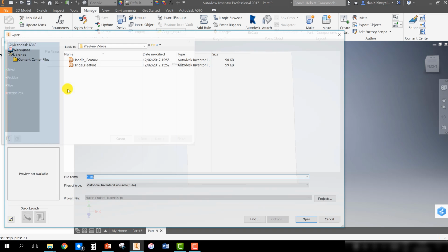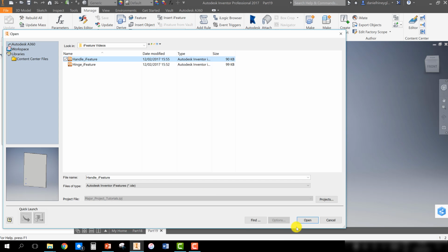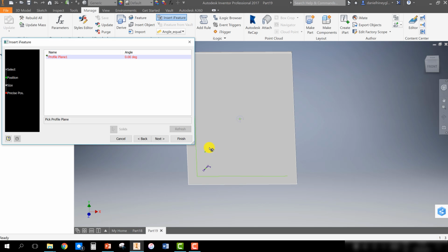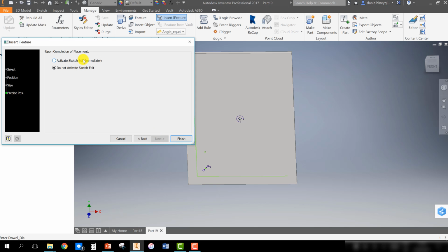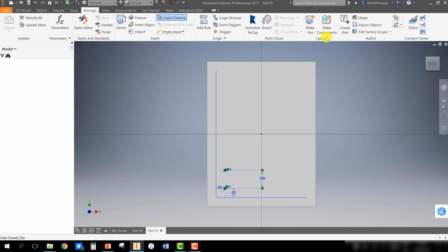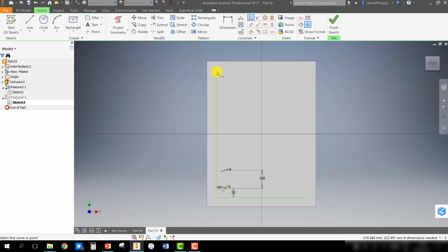Now every time we want to put a little handle on, we need a little handle hole. We just pop it on there. Next, your 4mm hole. If you want to change it to a 5mm hole, save a different size dowel, or and we're going to activate that sketch. Constrain the 3 points. There to there. Here to the corner.